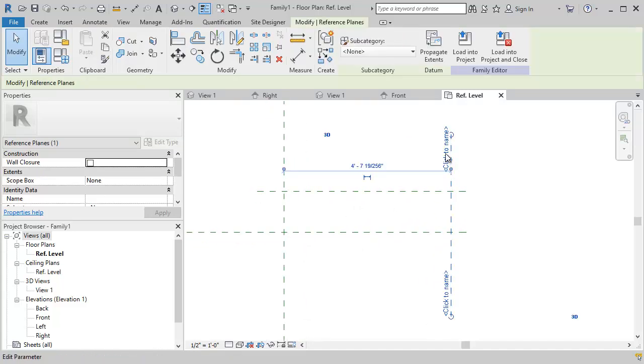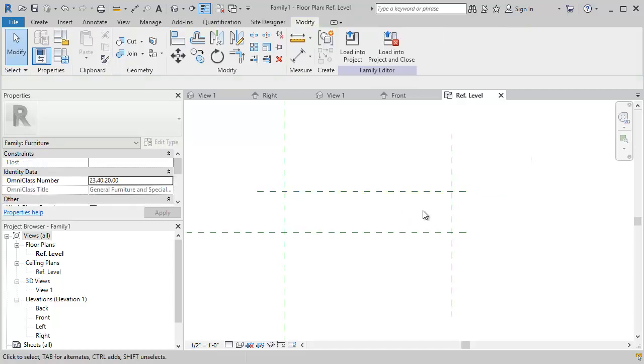So I do want to name these so I keep track of what they're going to be used for. So this will be shelf width, and this will be shelf depth. So I can reference those work planes in the future. I think it's going to make the most sense for us to create the extrusion for this in the front view. So we'll make the frame basically for the shelf, and then we'll make the back panel as a separate piece.